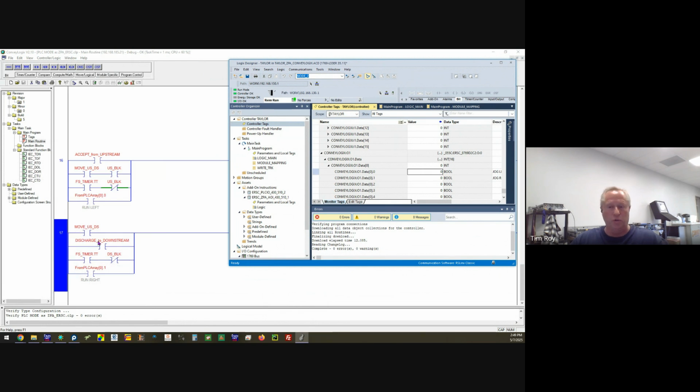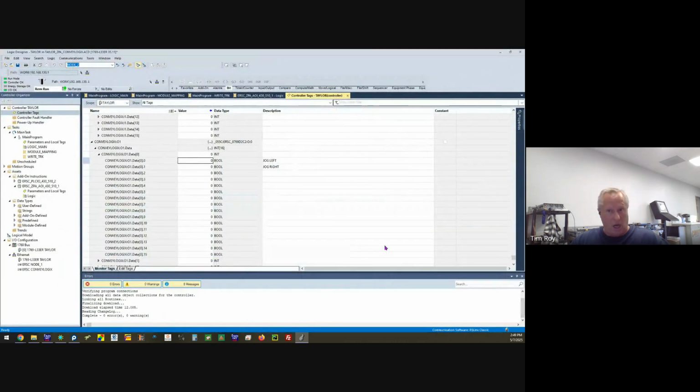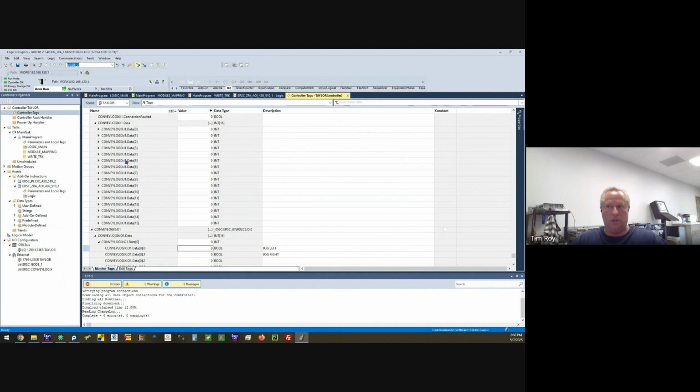So these two from PLC array tags, again, optional, but it's a way to have a ConveyLogix program running locally on the card, take some of the burden out of the PLC. But if need be, you could still handshake data through these ConveyLogix tags. You get 16 integers of inputs from the card, and you can write up to 16 integers back to the card.